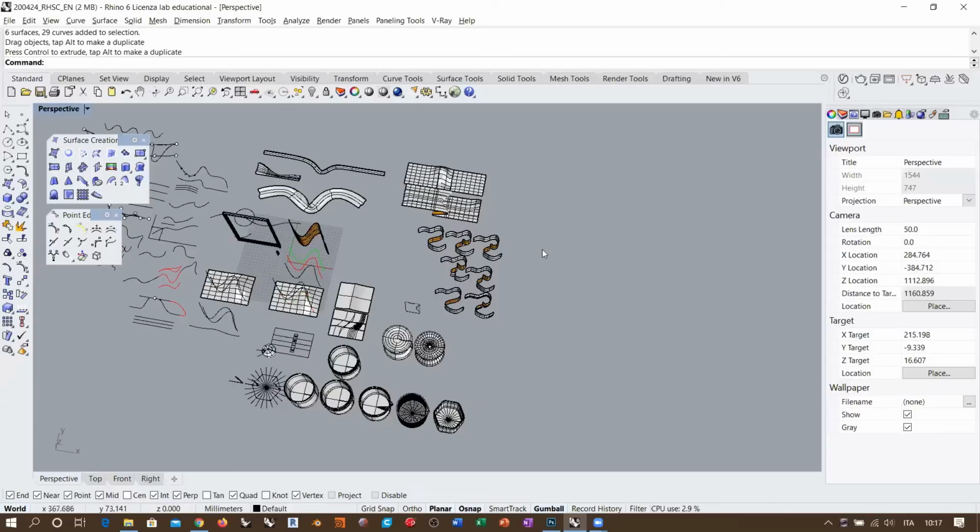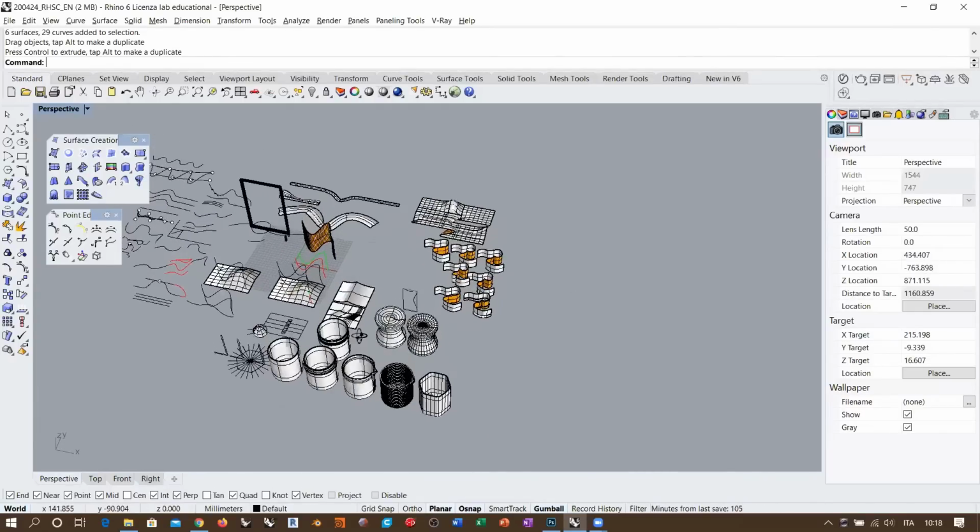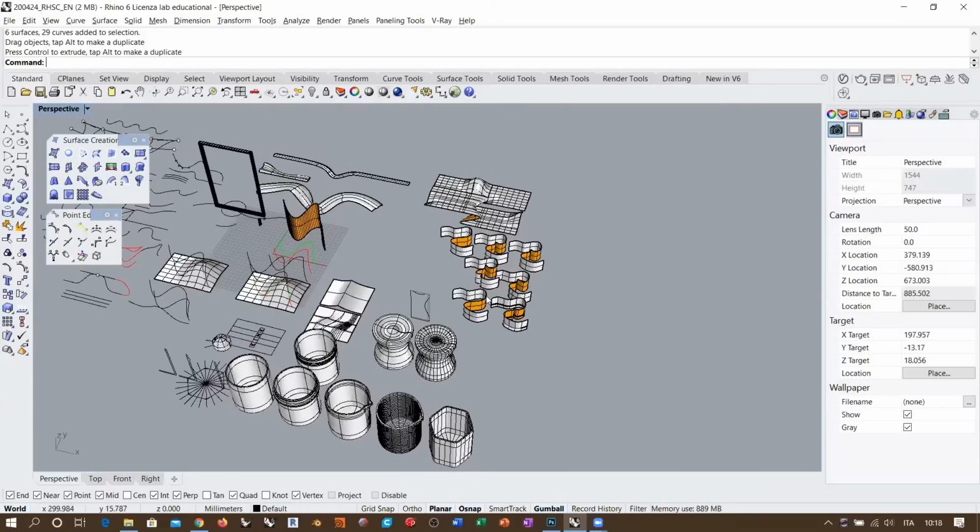Okay, as you can see, also the Revolve surface, which is a very basic command, when you analyze it from the topological point of view, has some tricks that you must consider in order to get to the right result in less time with less effort. Now let's go to the problematic surfaces. Which are the surfaces that I don't recommend using unless you are either at the end of the modeling workflow, so you basically don't need to do any other operation on that surface, or that kind of surface is absolutely the only choice you have for solving a very precise modeling step.